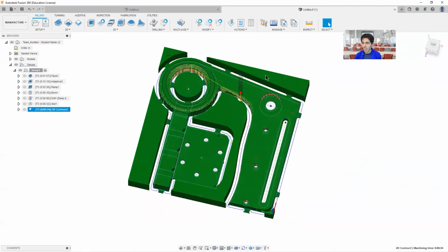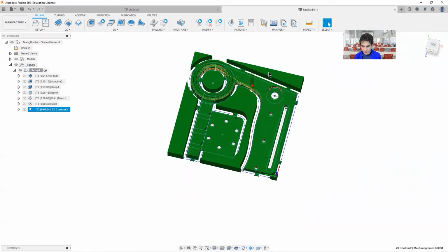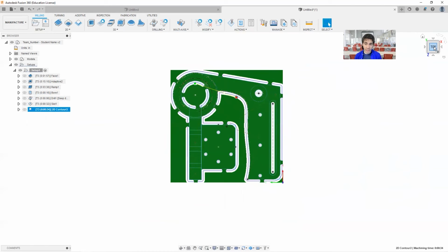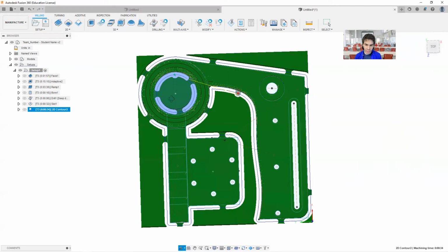It's better to have more tabs and then have more post-processing than to have too few tabs and then you have parts of your assembly just being pulled off, ripped out, and then being sucked up into the ventilation, which is a big headache and actually can risk both your part and the bit and the machine. So we've created a bunch of tabs.